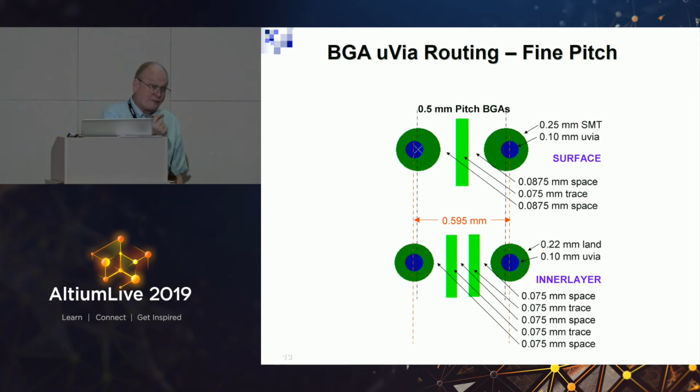Now, that's not a defect, but it does show up in X-ray. So it's not a blowhole, and these are not blowholes from the old through-hole days of wave solder, but it does show up, and OEMs don't like to see that in their X-ray. Before we had really, really good X-ray, they didn't know it was there. And it's perfectly reliable, but with the newer generation of X-ray, three-dimensional X-ray, it shows up that we've got a void. So we still have a big debate in the IPC about, well, how much of a void is permissible? And all the microvias, that void size is permissible and approved for class 2 and class 3. But assemblers don't like it.